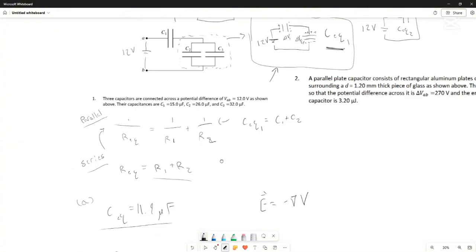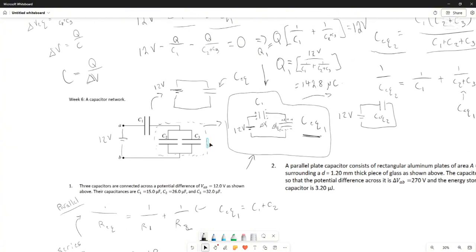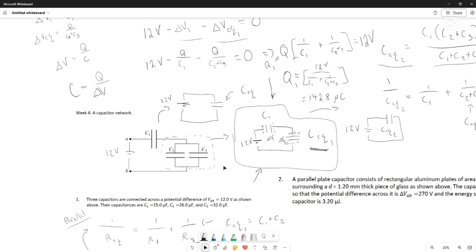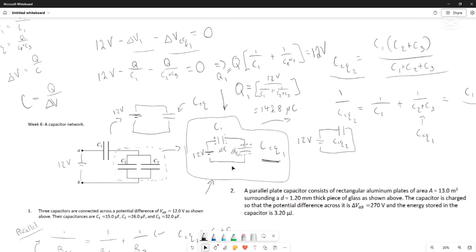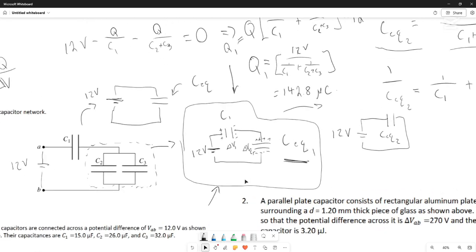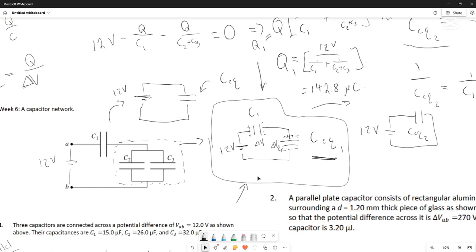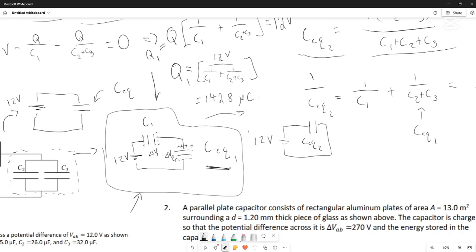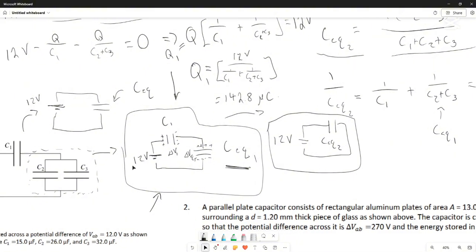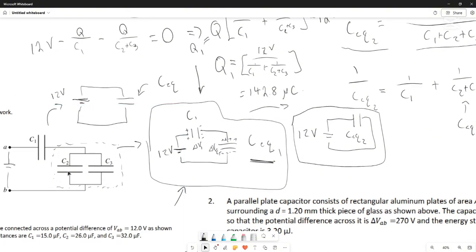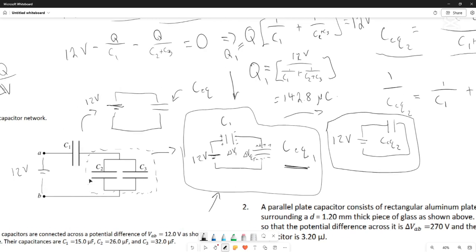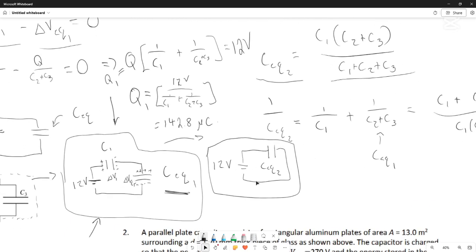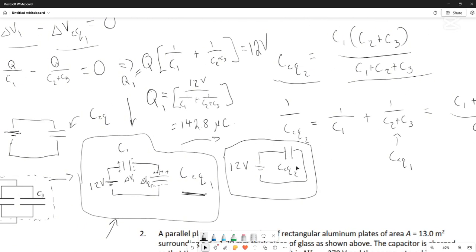Now, what if we want to get the voltage across C2 and C3? This is where, when you take the equivalence, you may or may not miss something important, right? Because if we go all the way to the third equivalent circuit, by breaking down this 3-component network to a one singular component network, we lose information that we need about C2 and C3.